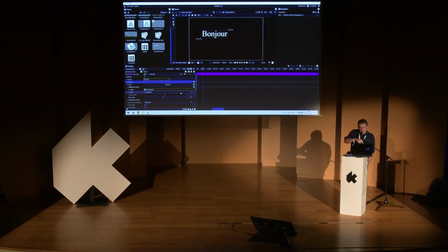In this case, the row index is a local setting. You have to unfold the parameters and access the settings to change it. But actually, you can define composition parameters. Composition parameters are global variables in the scope of the composition, and you can link these parameters to the composition parameters. So in this window, if you create composition parameters on the right here, you have all the exposed parameters, and you just have to select to change these parameters, and all the connected parameters inside the composition will switch to this value.